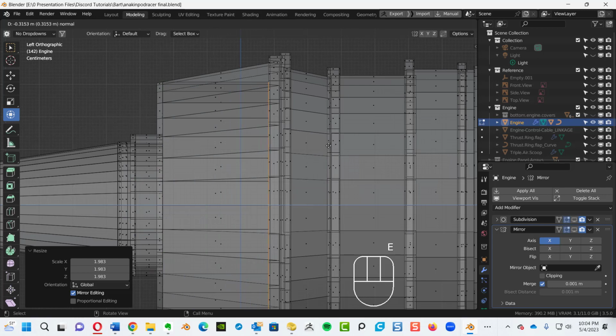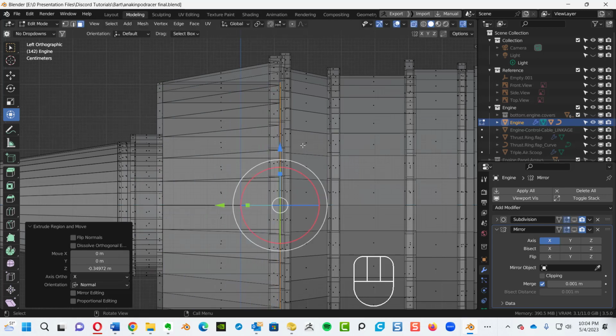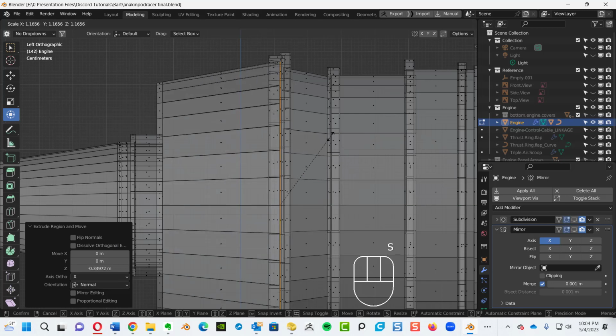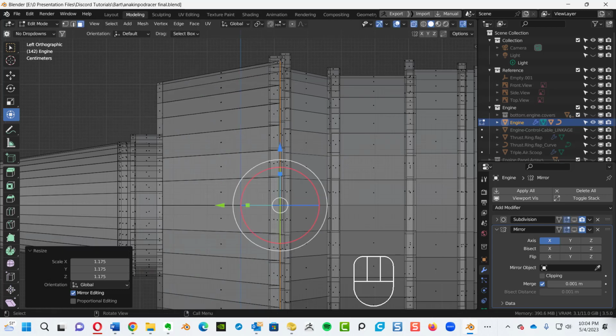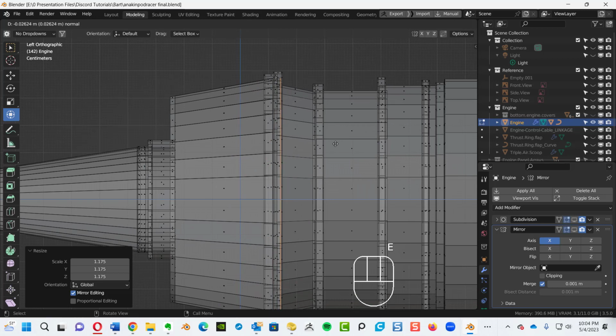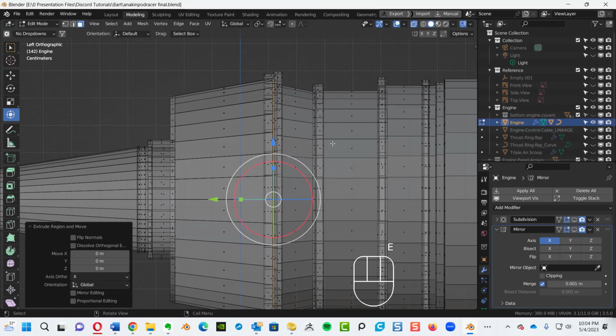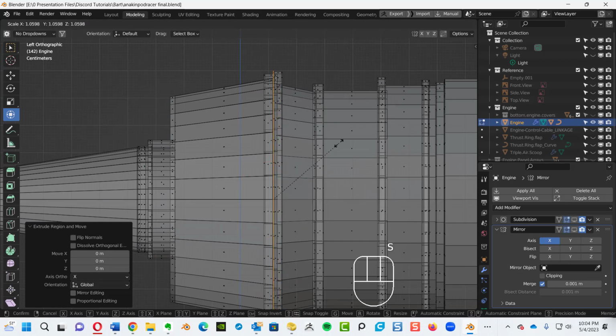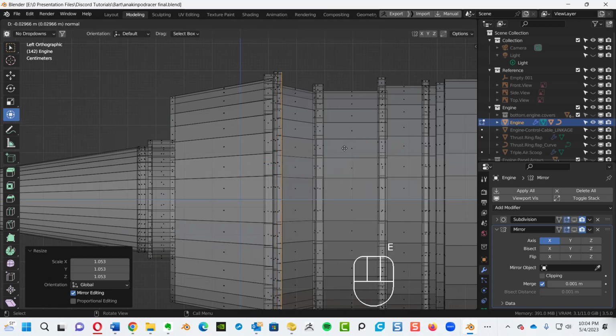Now, E key to extrude to the base, approximately where yours ends here. Now, I'm going to hit S key for scale again to match your right there. Okay. We're going to do this again. Same technique. So E key to extrude, right click to set it back, S to scale, pull it to there. So we're going to make this one solid object. Okay. E key to extrude it, pull it to there.